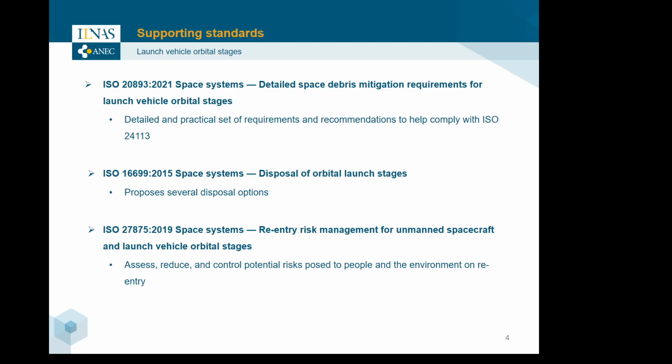Disposal is the process of removing the space object from the protected regions of space so as not to collide or otherwise interfere with the other users of those protected regions in the future. Disposal refers to maneuvers and passivation of energy sources, if applicable, after releasing the spacecraft. The standard proposes several disposal options depending on where, meaning what orbit, the launch vehicle is operating, so as to minimize interference with the most commonly used orbits, such as LEO or GEO. This standard is currently under review, as ISO standards are revised every 5 years.